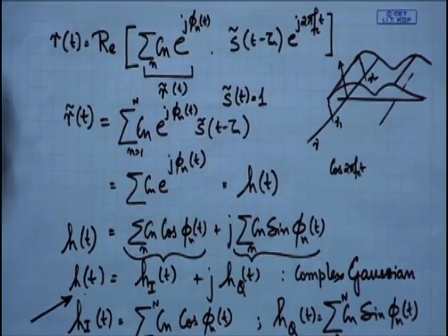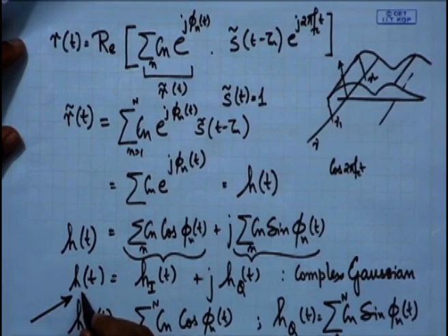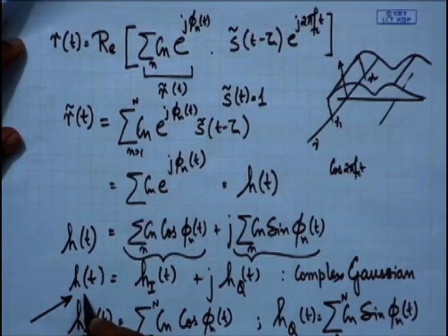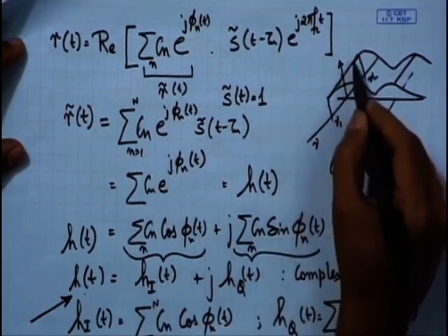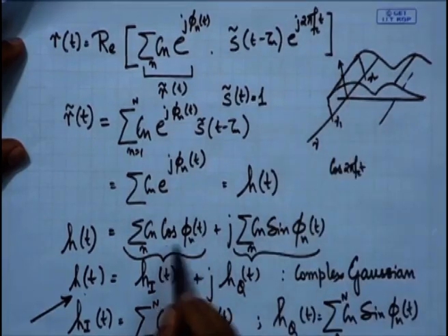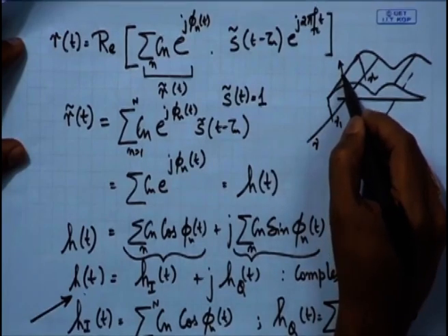So, what we see is that h, which is the channel coefficient, is randomly distributed. Now, this is one of the important things which we have said in the beginning, that we want to understand the channel, because understanding the channel will help us in designing transmitted sequences as well as devising the receiver structure. So, one important thing that we come across at this point is these channel coefficients are random. If you look at the flat fading condition here, we have values which appear random. It is complex, so it has a real part and an imaginary part, and the distribution is complex Gaussian.